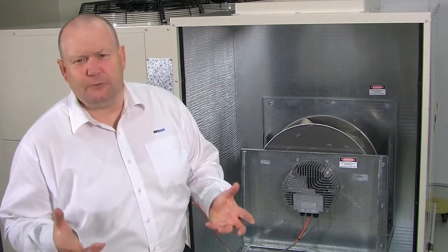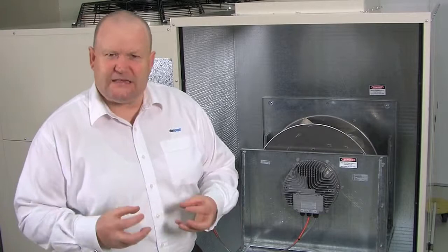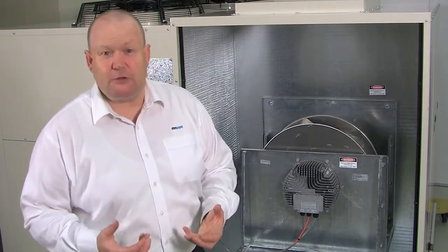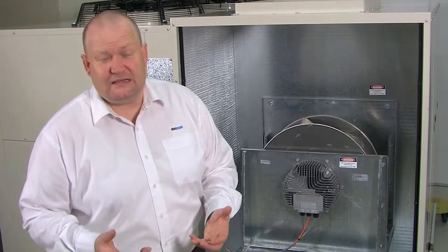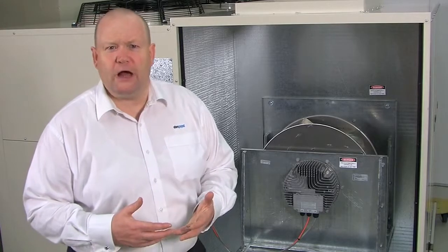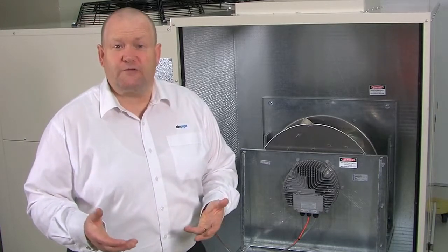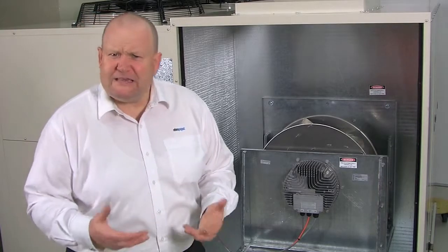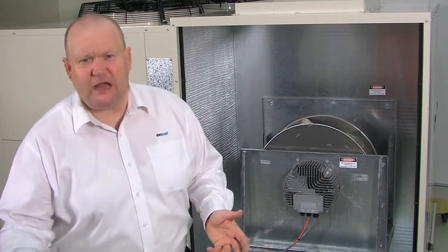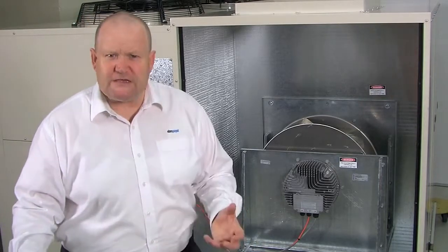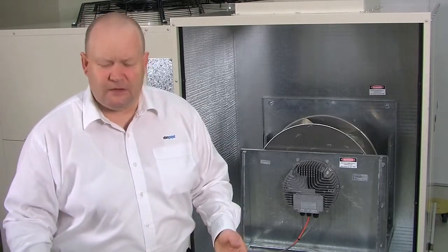And what's EC? What does that mean? Well, EC is a motor technology. An EC is a permanent magnet motor with onboard electronics. This allows you to give the motor three-phase as well as a speed control line, such that you can speed control the product from 100% down to 5% speed. Now, typically EC products are getting used in a range of applications, from refrigeration to air conditioning to ventilation. And the reason is because of their high efficiency.